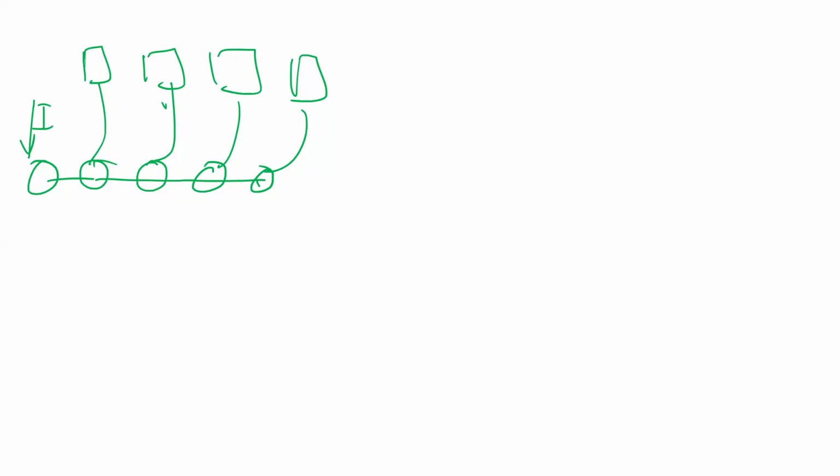Now, you took a transistor yesterday when you did it, what was your GM value and what was your RDS value, roughly? So RDS was almost, let's say, 500K, right? And GM was what, roughly? So let's say 1 millisiemens typically, so 1e minus 3, right?